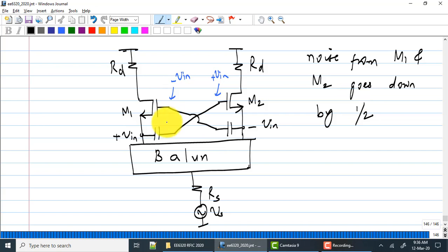That's number 1. This circuit, however, is relatively broadband. You are limited by gain A, but this is broadband. I'll put it within quotes because unfortunately the balun will now limit the bandwidth of performance. Remember that the antenna is still single-ended.